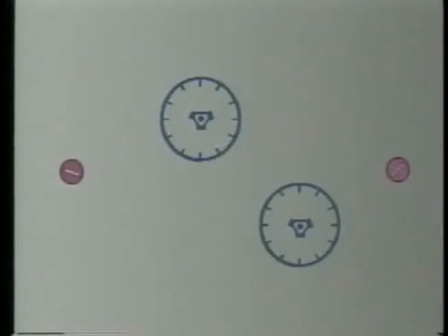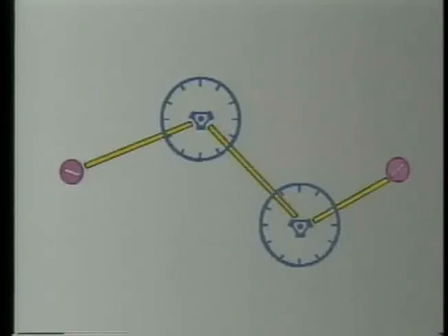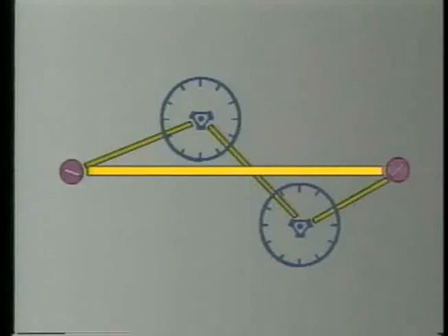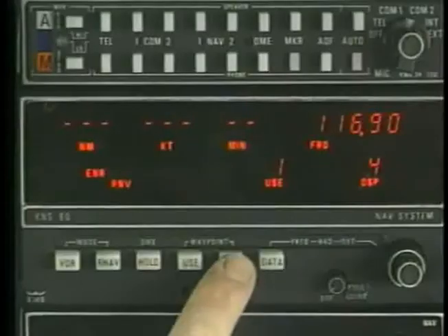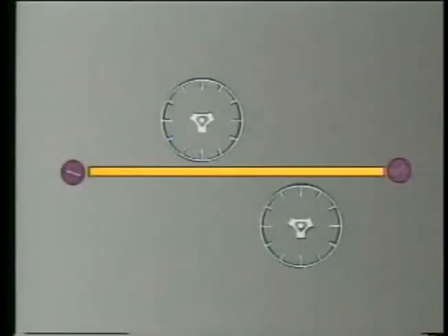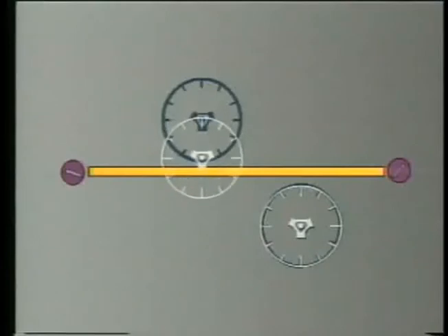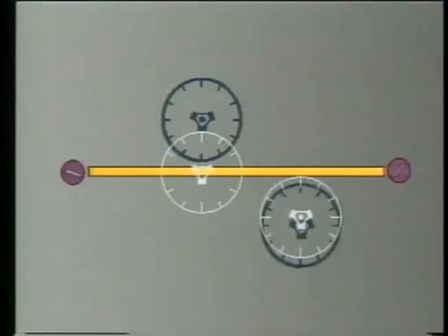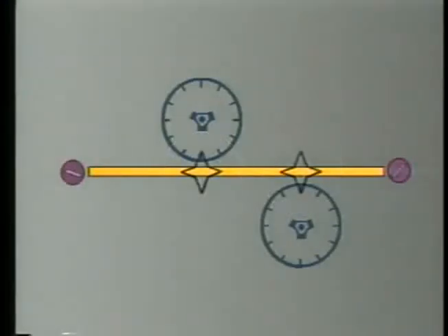As you learned earlier, VOR provides for navigation between stations. But VORTAC-based area navigation allows you to fly directly to your destination, often with considerable savings in time and operating costs. To accomplish this, a course line computer allows you to electronically relocate or offset navigation aids to a desired radial and distance from the original location. These offset stations are called waypoints.